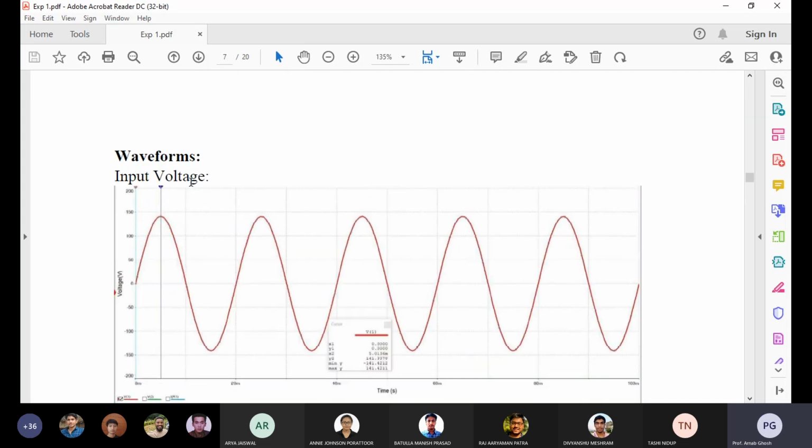Another thing I have forgotten: after the observation table, you will plot one graph in an Excel file. Your x-axis will be different values of R, and the y-axis will be voltage, current, and efficiency. You see how the system performance varies with the load resistance, how the voltage changes, whether it is less or the same. You plot this in a single graph. But what is the problem?